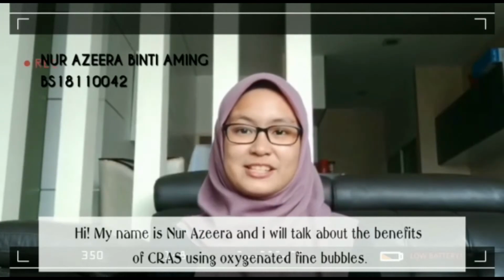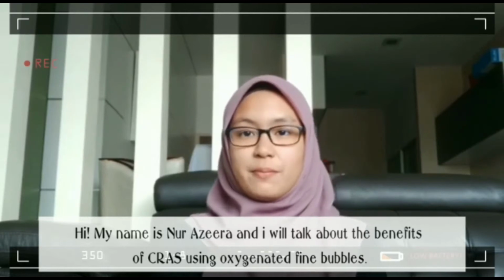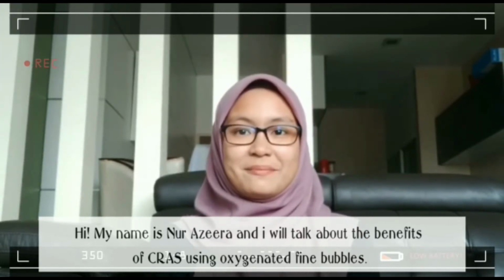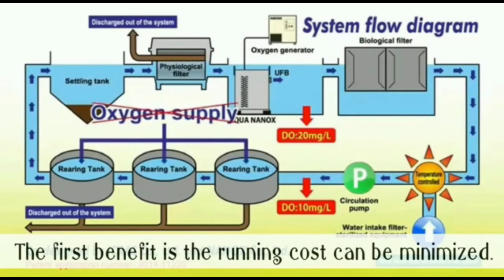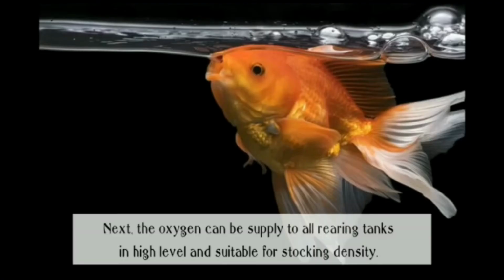Hi, my name is Nur Azira and I will talk about the benefits of CRAS by using oxygenated fine bubbles. The first benefit is the running costs can be minimized. This is because CRAS with oxygenated fine bubbles does not need an oxygen dissolver, carbon dioxide deaerator, suction unit and ultraviolet sterilizer. Next, the oxygen can be supplied to all rearing tanks at a high level and suitable for stocking density.